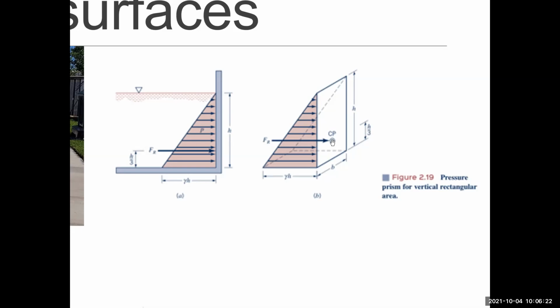And to find that location, we need to use your statics knowledge, with center of pressure, centroid, moment of inertia, those types of things. Only for this part, we will find the location of the force also. Since this is a triangular one, if you can remember, the location is actually 1/3 from the highest load or 2/3 from the lowest load. But we will calculate that. Okay.